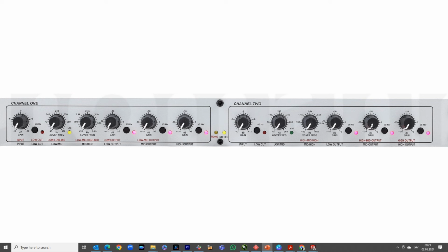It is very important, and it may happen that there is a sensitivity difference between one channel and one speaker and another speaker, the mid-range speaker. What you have could be 2 up to 3 decibels for a worst case scenario. For good manufacturers it is lower, so don't be afraid that they will not match here on regulations. Your hearing is the main thing which should be taken into consideration.